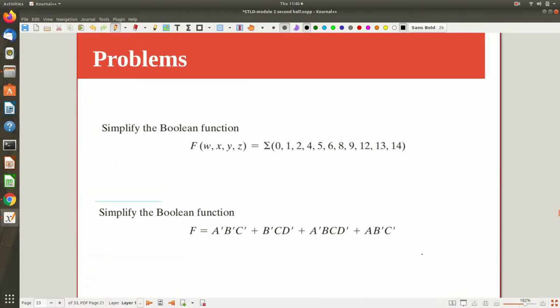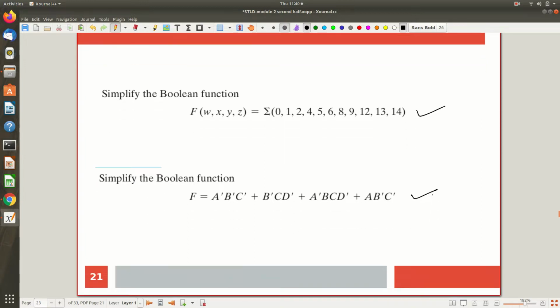So sometimes they can give you the question in the canonical representation, this sum of products, sum of minterms, sigma expression, or sometimes it may be given in a form like this, and you know from this representation how to make the other one. So you can go like that. What you can do is, this is nothing but equivalent to a' b' c', which is missing a variable. This is a 4 variable expression, so I think it is f of a, b, c, d, and you can see that d is missing.